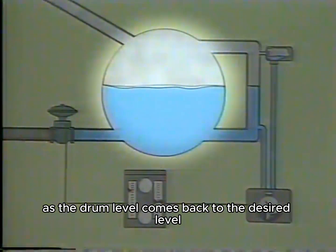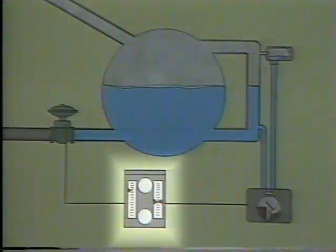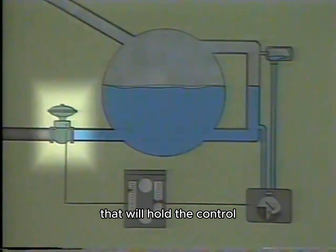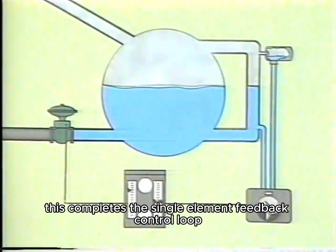As the drum level comes back to the desired level, the signal generated by the level transmitter is fed back to the controller. When the feedback signal is equal to set point, the controller produces a signal that will hold the control valve in its new position. Now, this completes the single element feedback control loop.